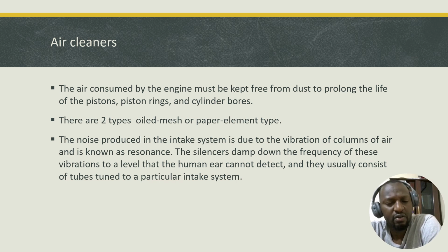So if you allow this kind of air to go into the engine, it is likely to cause abrasion, because dust contains sand particles which are very abrasive, and they increase the wear of the cylinders, the pistons and the piston rings. So to prolong the life of the engine, we need to make sure that the air going into the engine is clean. Now there are 2 types of air cleaners used. We have an oiled mesh or a paper element type.